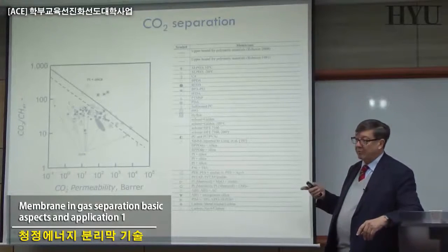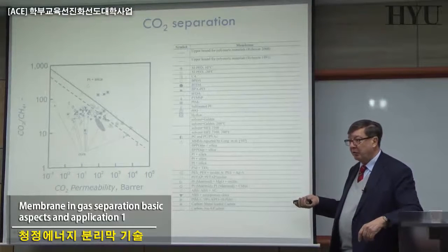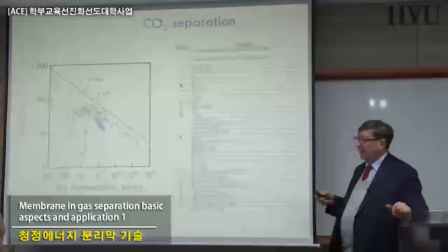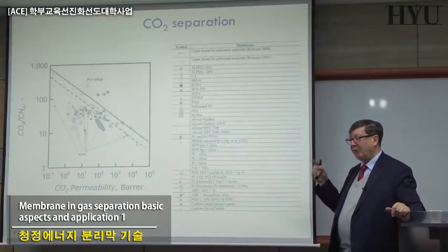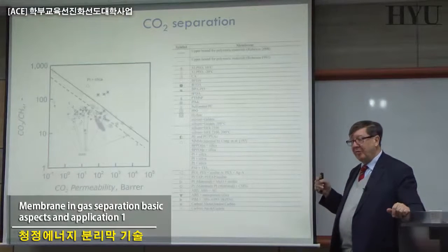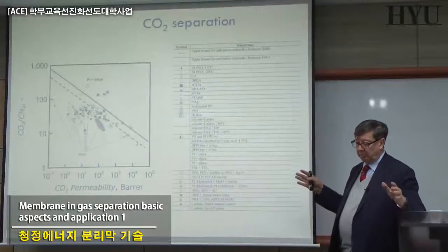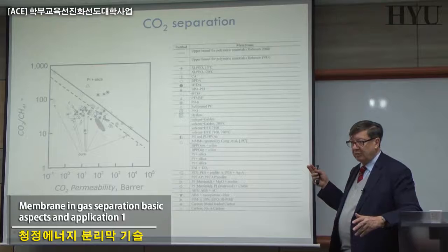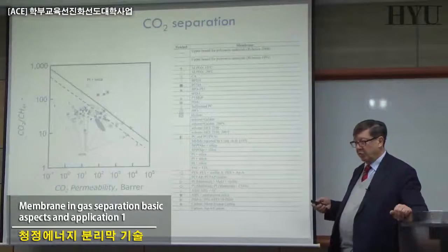But if you want, for example, to use enriched oxygen for a combustion problem, or another system where cost is important, today in the range of 25–40% of oxygen you can compete with cryogenic production, because at a relatively small concentration you don't need very high selectivity, and this plant normally can compete with cryogenic in terms of cost.